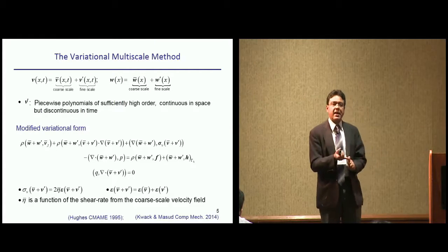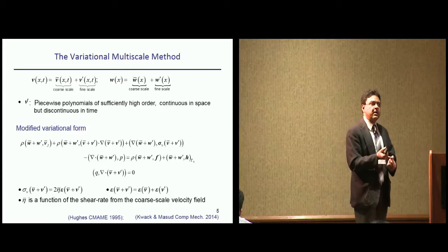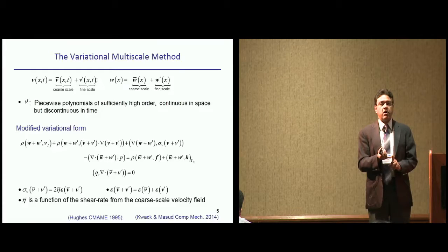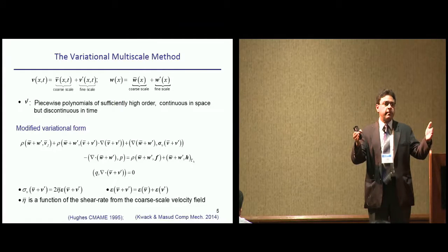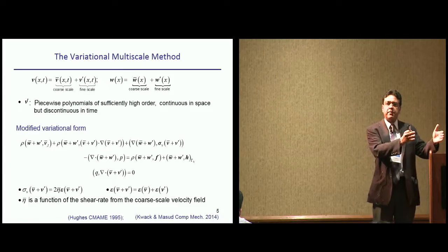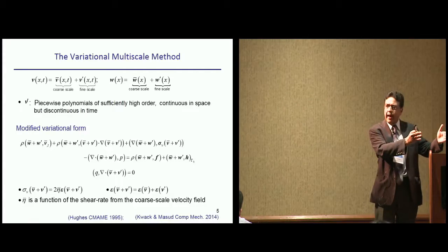So the question to ask is: is it possible that we can live with cruder discretizations and can somehow model the features in the flow that are smaller than the size of the element? So now, think of the total solution. With a good method, let's say if we can capture the total exact solution, a part of it can be captured with a good method, and a part is filtered out. So what is filtered out is in fact the error, and error is also a solution to the problem.